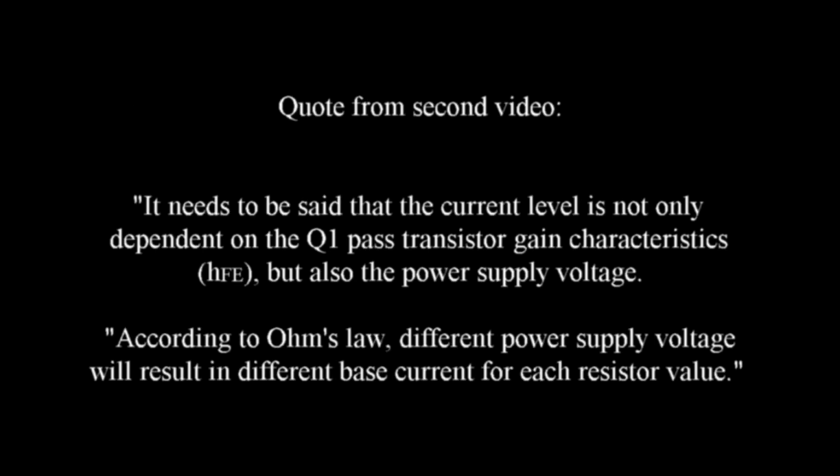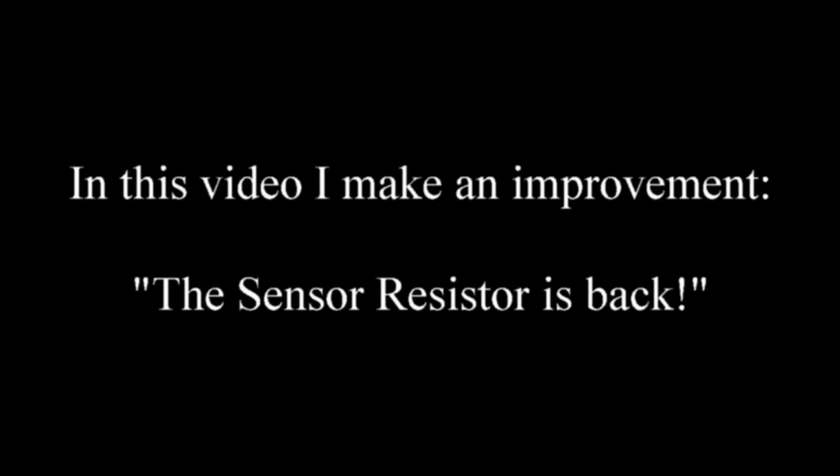Quote from the second video: It needs to be said that the current level is not only dependent on the Q1 pass transistor gain characteristics, but also the power supply voltage. In this video I make an improvement.